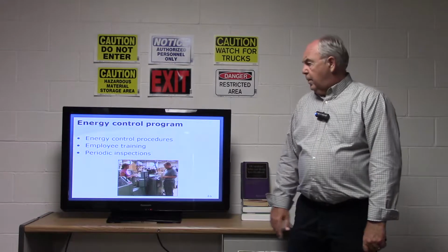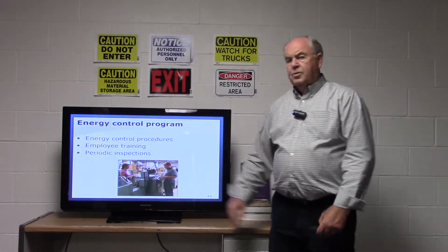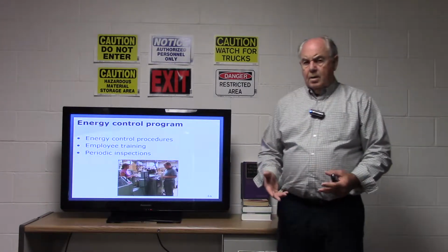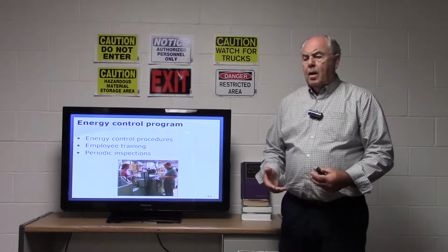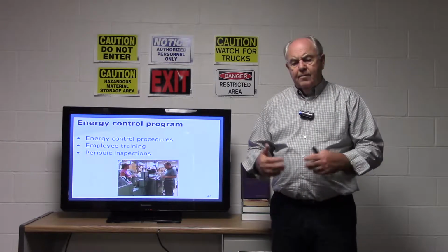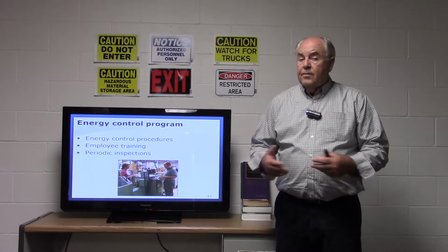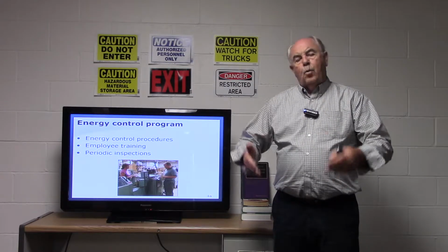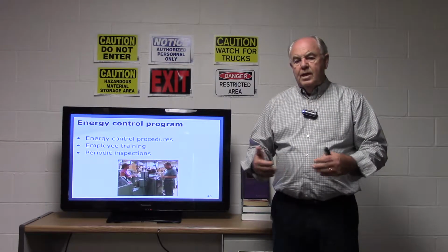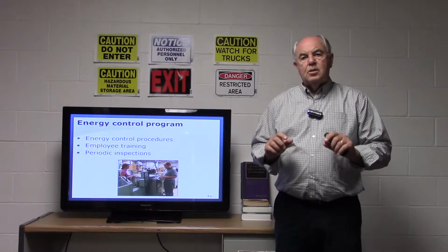Energy control program. Energy control procedures consist of a written lockout tagout program. Now the lockout tagout program will identify the different steps, the different pieces of equipment, and what the lockout procedures are for each piece of equipment, machine specific.